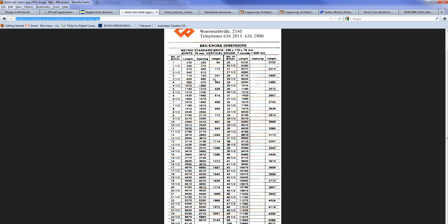And what I'll do is I'll show you a screenshot of what I've drawn on the board so that you can really start to get an idea of where I'm going with all this discussion of 2914 and so forth. So just bear with me for a second. But what I'll mention is that the 6 courses of brick would be 514 plus the 2400, which is a very comfortable dimension for your concrete blocks, and will add up to 2914, okay?